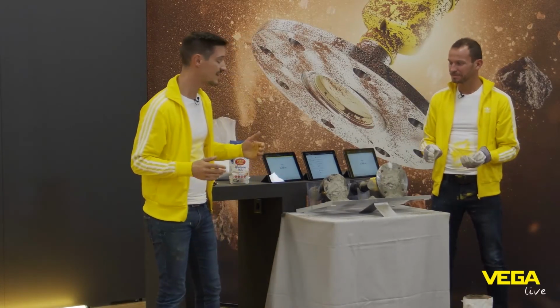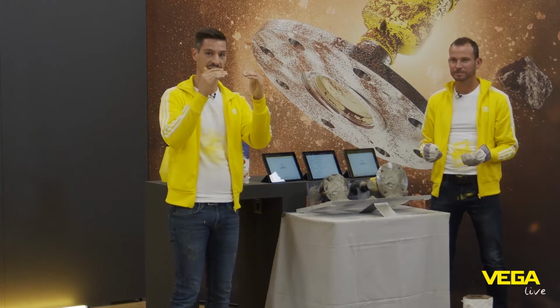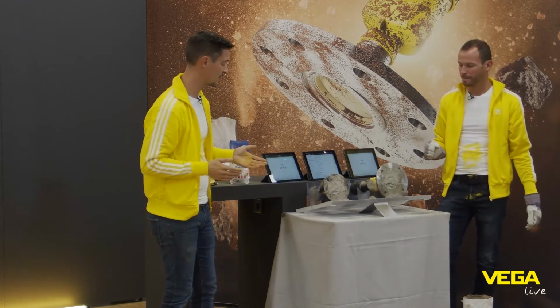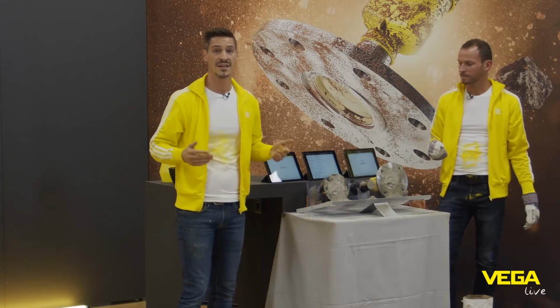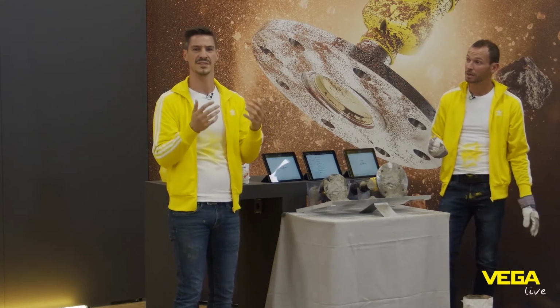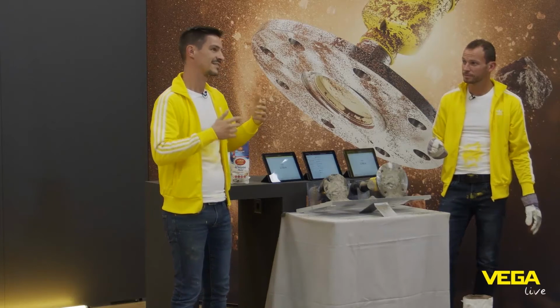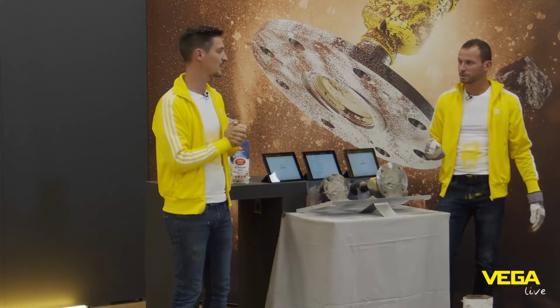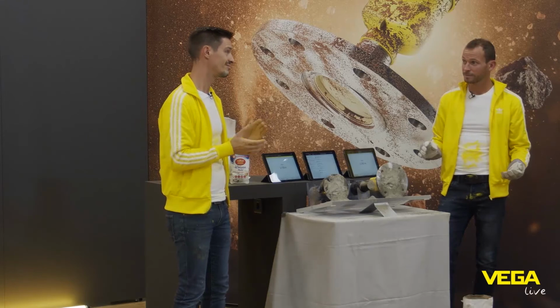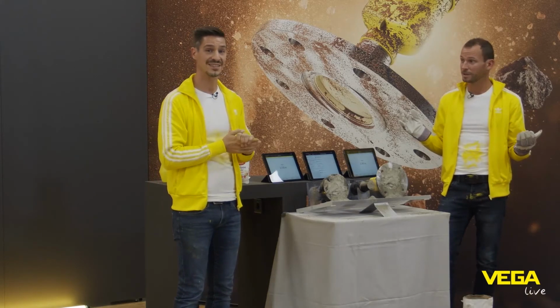Self-cleaning effect means that due to the movement of the membrane, all the build-ups will be removed by the sensor itself. But obviously, we are looking at these heavy build-ups. The energy of the sensor is not strong enough to remove it. So therefore, this self-cleaning effect is more or less something which I have never seen in real life. Therefore, I don't believe it exists.